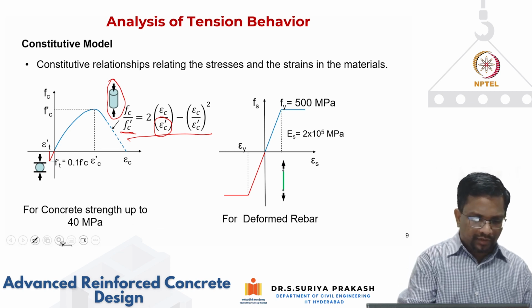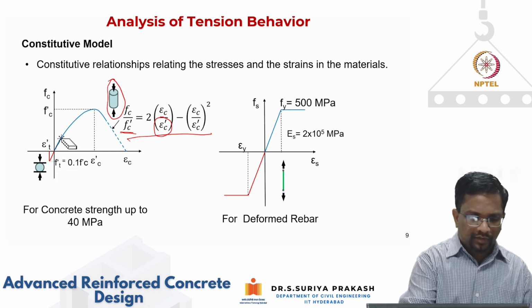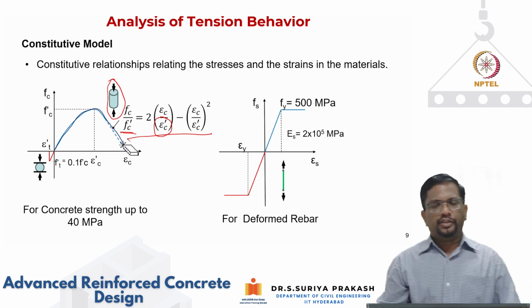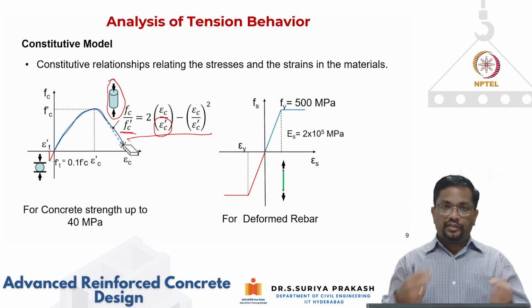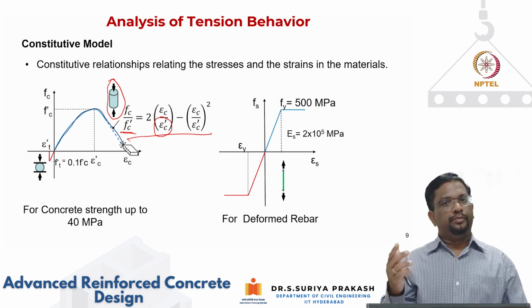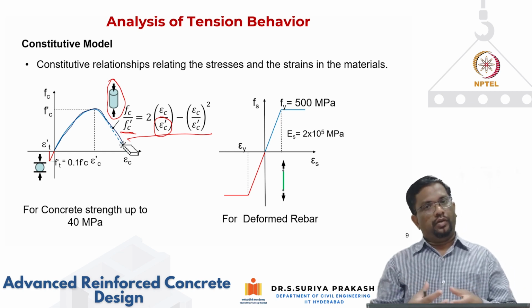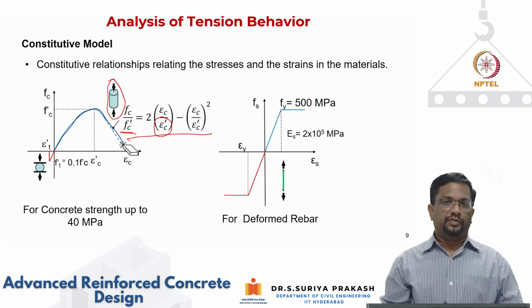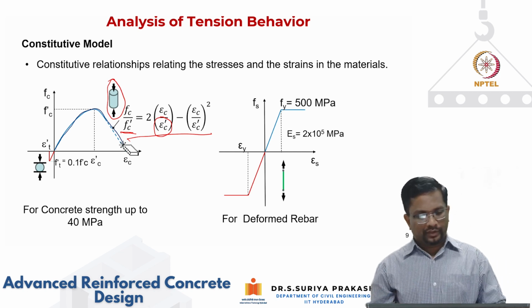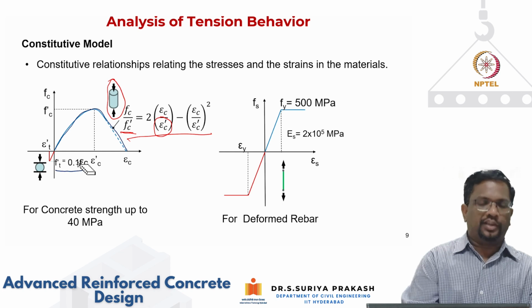nice parabolic relationship. Okay. Similarly, how the concrete is going to behave in tension, we've studied that. Doing pure tension is always difficult. So either people do the modulus of rupture test, or people do the splitting tension test, which is also called the Brazilian tension test.